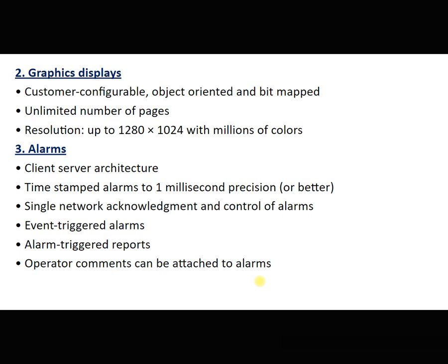Next, event triggered alarm. In the sense, any emergency turned on, that is one event. At that condition also you are going to get one alarm. Any CB is tripped, that is one event. Again you are going to get one alarm. That is the event triggered alarm.